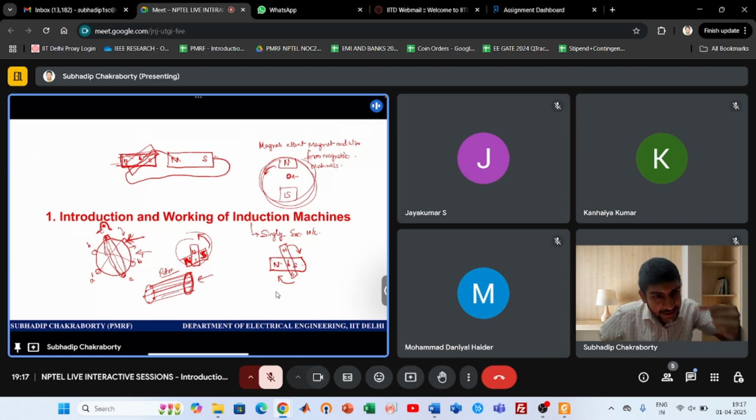Now, since the magnet is virtually rotating, what does the rotor current want its flux to do? It wants that there should not be any flux, because earlier the rotor was sitting with no flux. You plugged in the power source that generated the rotating magnetic field. The rotor currents will produce flux so as to oppose the main flux. How can it do so?